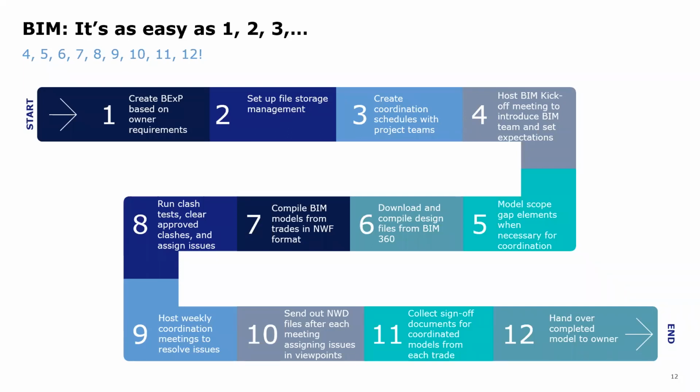How do these efforts on BIM make it to the guys in the field? And what if there's a discrepancy between that 2D construction document and the model coordinated in BIM? Yeah, so the 2D plans always rule. If there's a discrepancy, you always go with the 2D plans because that's what's in the contract. But ideally, you make the 3D models based off of the 2D plans, or even architects will make their models in Revit and then export 2D plans from that.